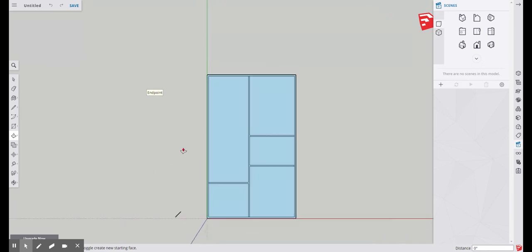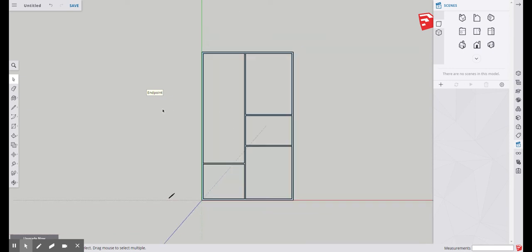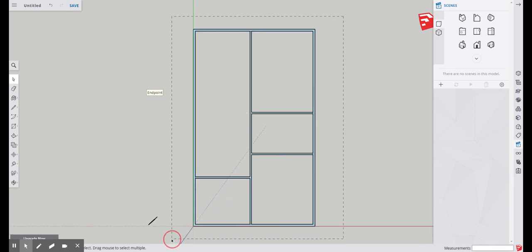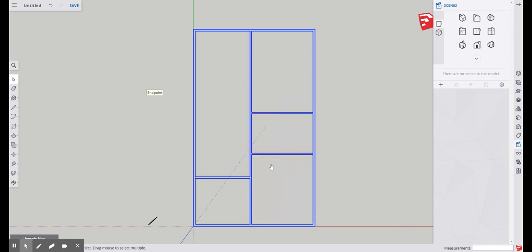So you go back on the top view and you can click your selection tool and make sure that surface is selected and hit delete. Surface selected, delete, and do it for the rest. And now we just have our outline of our walls. Because I just wanted my walls, I click, get this little box around, and let go. And that's going to select all my walls. What we're going to do is right click and group them together. Make group.